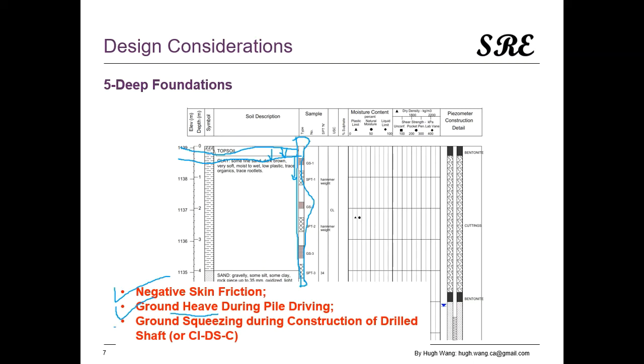If we decide to use drilled cast-in-place concrete piles, then during construction you need to watch out for squeezing of the drilled hole before you place concrete. Because the clay is very soft, it could squeeze into the hole. Definitely, casing will be required.